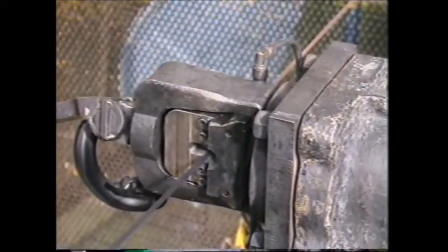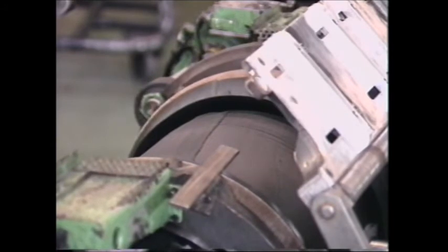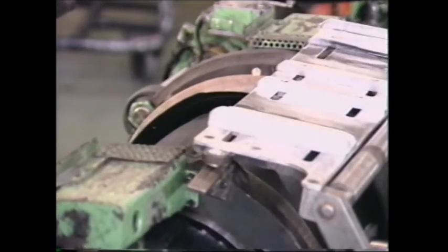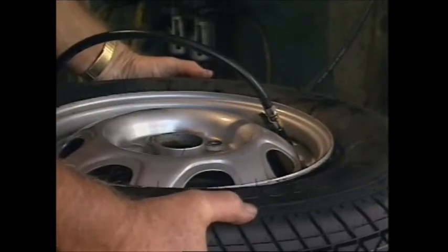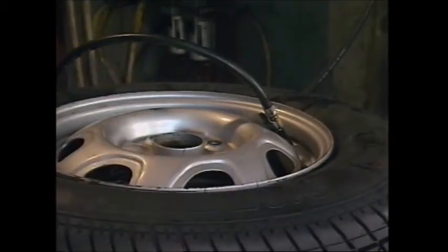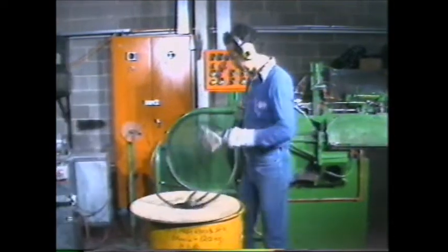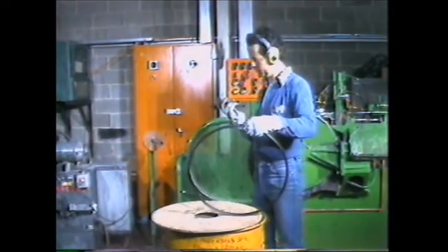The bead of the tyre is made of a cord of high tensile steel coated with rubber. The end of the ply is wrapped around the bead, which is then wrapped in rubber to stop chafing of the plies and also to seal the bead against the rim. The length of the wire used for the bead determines the rim diameter of the tyre.